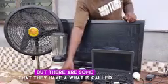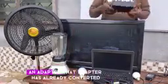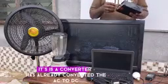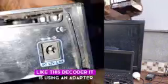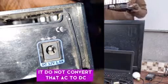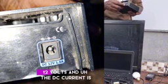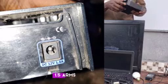But there are some that have what's called an adapter. That adapter is a converter that has already converted the AC to DC. Like this decoder, it is using an adapter. So you plug the adapter to your AC outlet, it will now convert that AC to DC, step down the voltage. So what you'll be having, the input here is DC 12 volts, and the DC current is 1.5 amps.